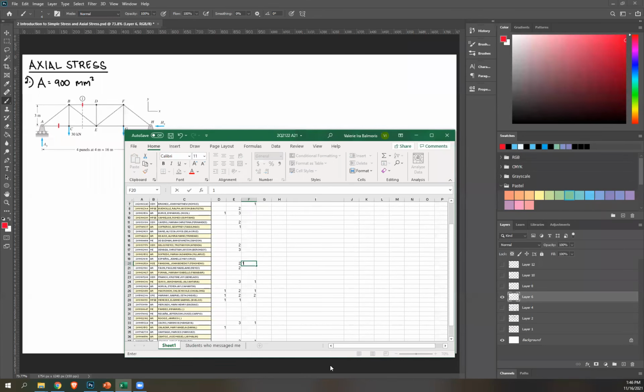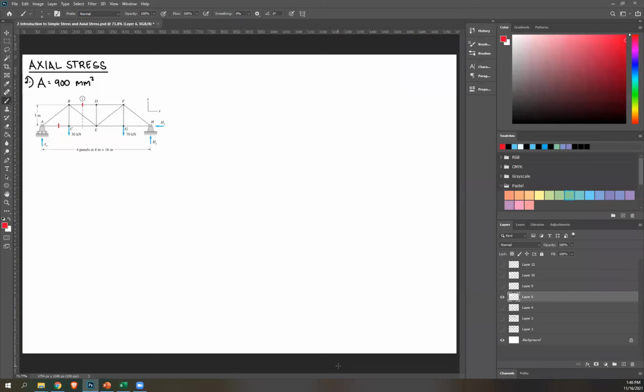joints. Now it's possible to do method of sections, okay, it's fine. But typically, since AC is directly connected to a support, we can use method of joints. Okay, so let's start at A. As you can see here at this joint, I have this support. So I have to solve for that support reaction first.